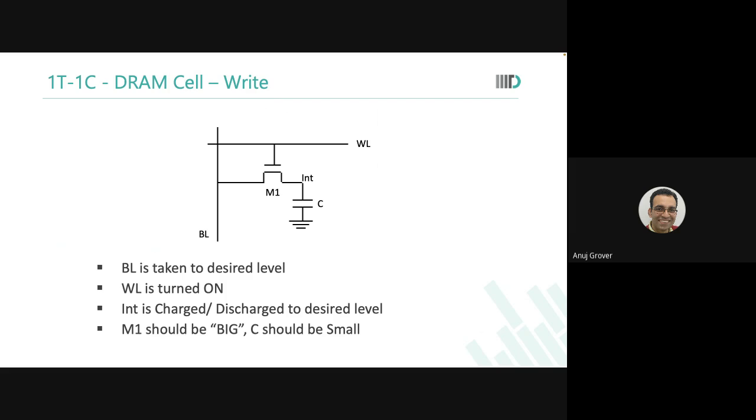We know this. So if the temperature of my DRAM increases, I will need refresh more frequently. If the VT of my pass gate is reduced because of whatever reason, whether it is a fast slot or I'm running on forward body bias because I wanted speed, whatever it is, if the leakage of the pass gate is larger, I will need a faster refresh rate.